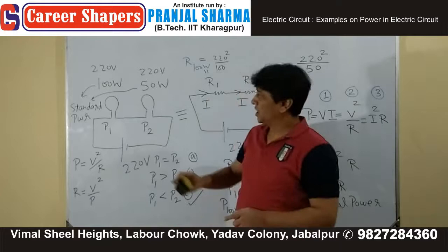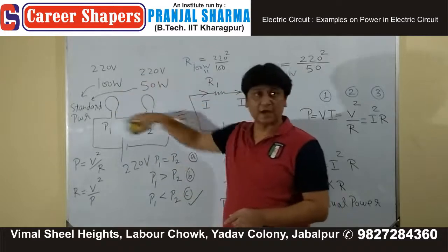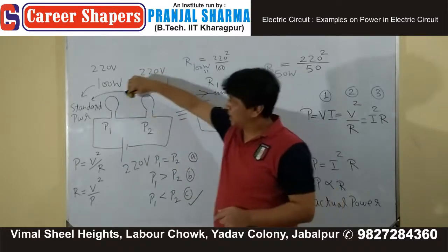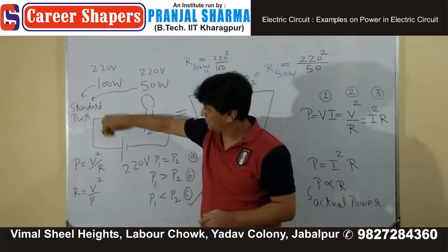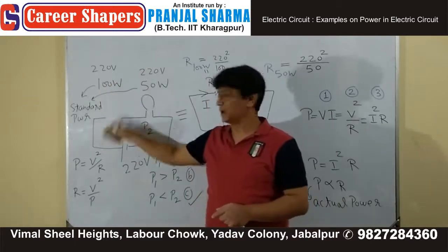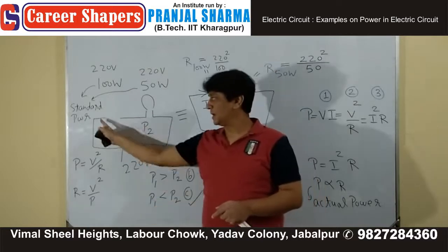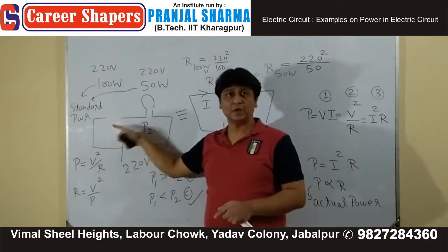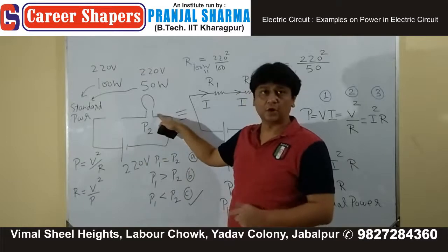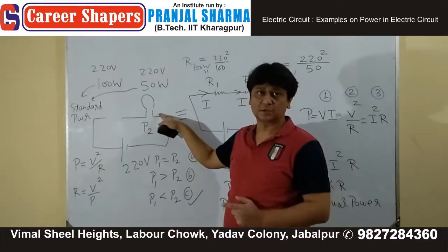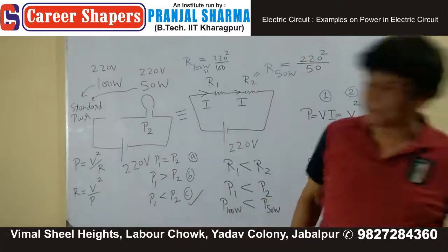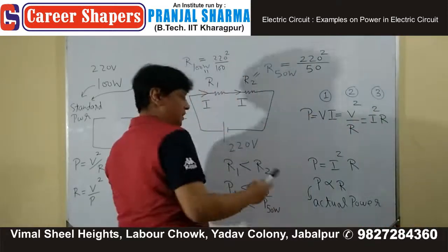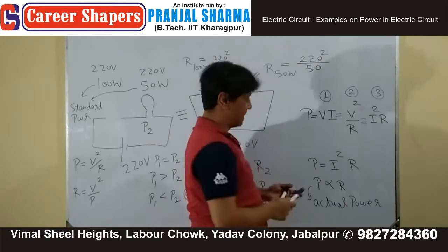The reason is, if they are connected in series and one of them does not work, current cannot pass through it, and then the second thing also becomes useless. Therefore, in household supply, you will find that things are connected in parallel.